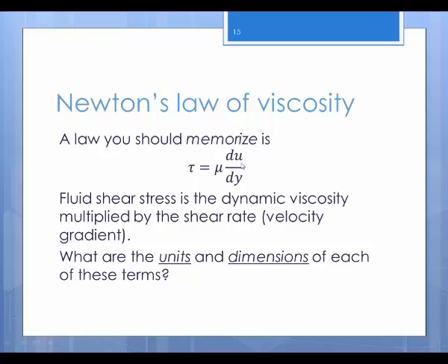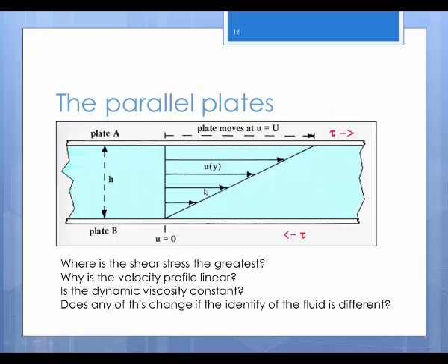And the shear rate, when you look at it in a diagram, is the change in velocity with the change in position. If you take velocity here as meters per second and divide it by just a coordinate, meters, then meters per second divided by meters is just per second, or 1/s. So a shear rate or a velocity gradient is just inverse time, which is probably not what you might expect. But if you combine inverse time with something like Pascal seconds here, or centipoise for absolute viscosity, then you will end up getting something that's a force per area.